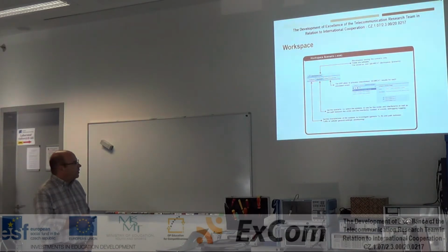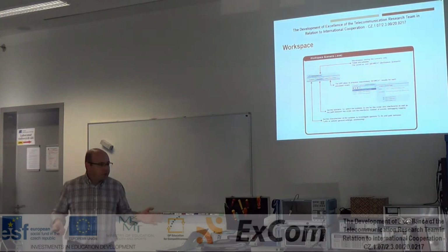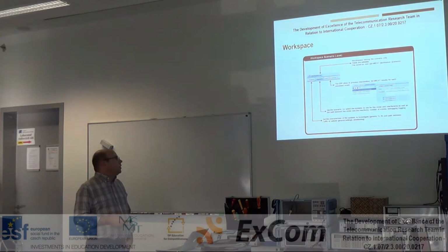Then we have the scenario, and the scenario will set how far the systems are from each other, and which propagation model will be used between them. The scenario will also set the relationship between the systems for the victim and the interfering link. And finally, the event processing can be used to see intermediate results for the simulation process.